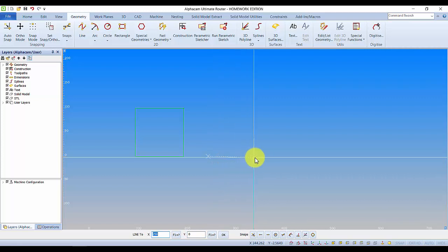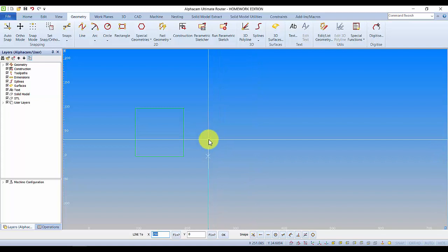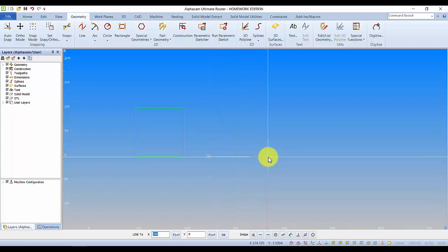Then moving across, let's go up this way actually. Let's move horizontally. So let's go 350. Remember, that's 250. I want to add on 100, so I'm moving over to the right another 100. So this point is 350, tab 0, enter.